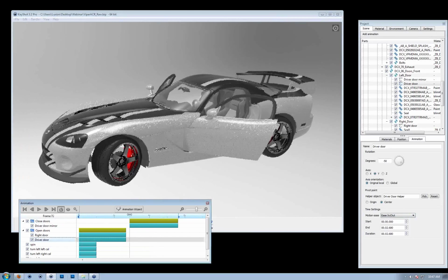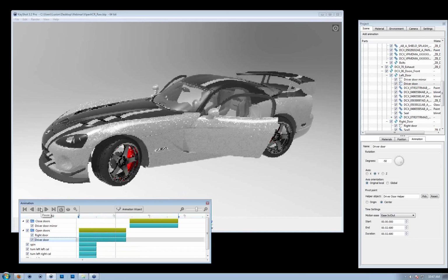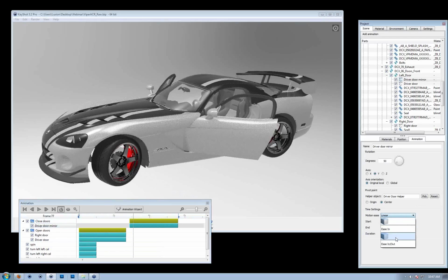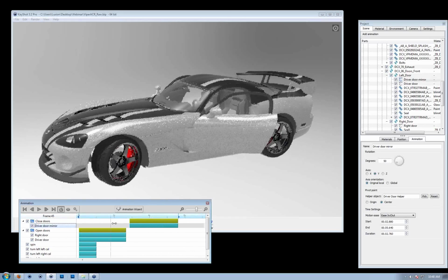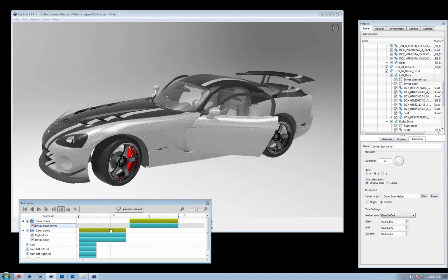And of course, you're going to want to use a lot of ease if you really want natural motion, because nothing happens very linear in real life. And we'll just do that here as well. So since we don't have a curve editor, you're limited to linear, ease in, ease out, and both. So if you wanted to accelerate and then stop linear, you can do that. But of course, most of the time you'll probably just throw ease in, ease out on there. So that's where that is.